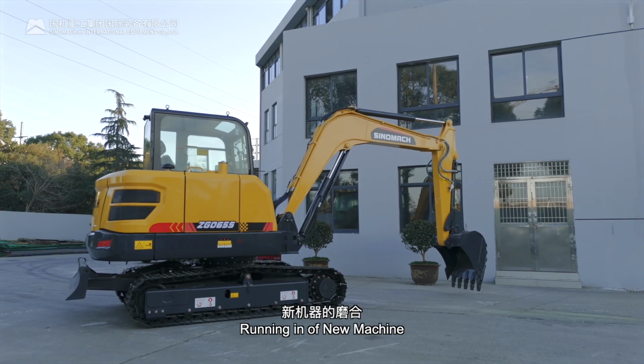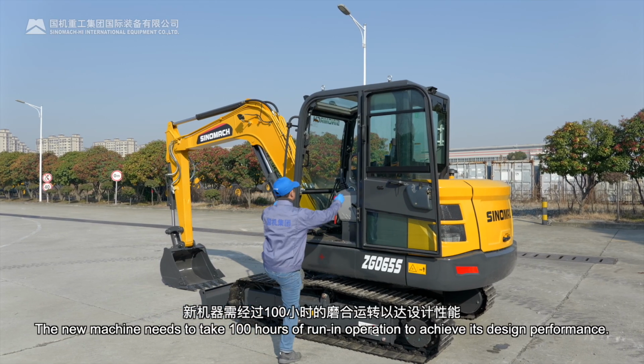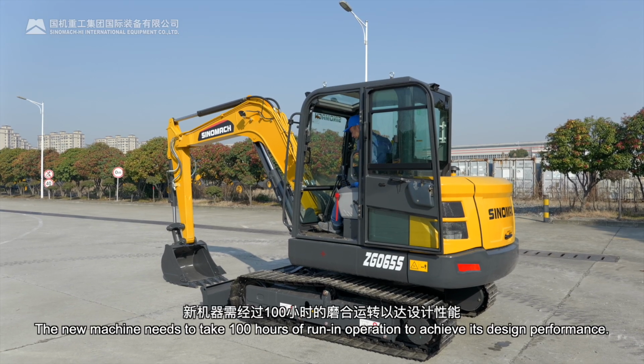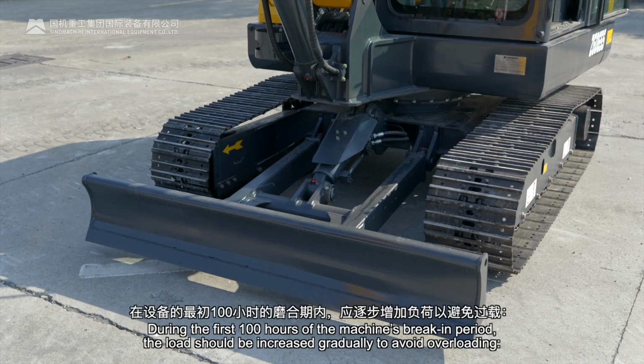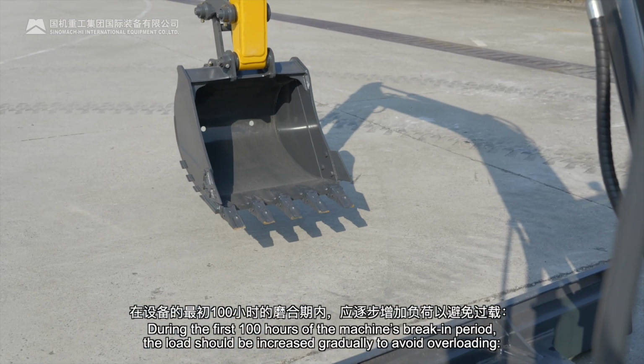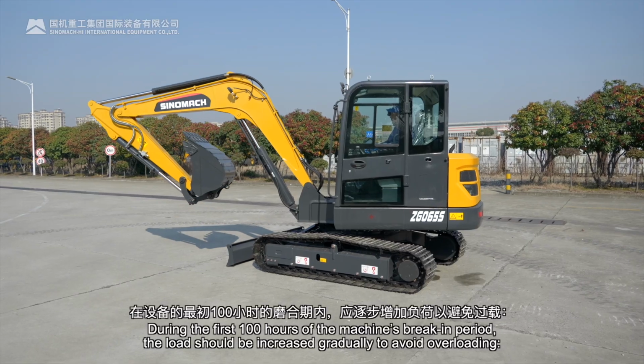Running in of new machine. The new machine needs to take 100 hours of run-in operation to achieve its design performance. During the first 100 hours of the machine's break-in period, the load should be increased gradually to avoid overloading.